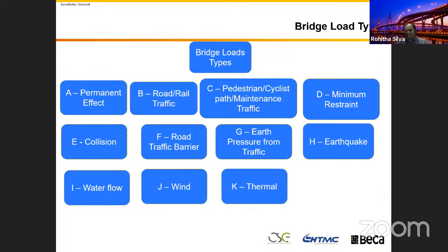When you finish your bridge design, you should know which load case actually governs, and where you put your truck to produce the governing load case. For example, if you design your pile or column, which load case governs? Sometimes it is governed by the collision, sometimes by the earthquake, sometimes by the water flow, because for some bridges, like in this picture, the height is 50 meters and the total height of the bridge is 120 meters. These loads may govern, even the wind. You should be able to tell.